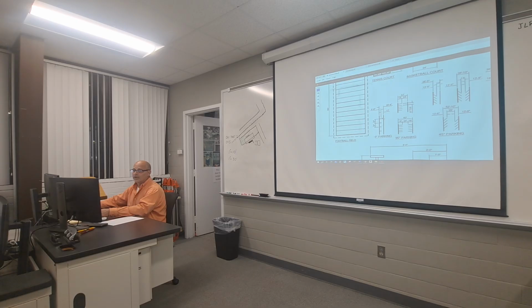So once again, maybe yours has some on the outside. Maybe, I'm gonna give you your number in a minute, but maybe you counted and you were 4 short of how many parking spaces the customer said they wanted. You could just throw some of these along the side somewhere, wherever it fits this design, boom, there's your extra spaces. If you choose to do your standard 90-degree parking spaces, so you're going to be designing a parking lot, and I will give your quantities in a moment. You're gonna be designing a parking lot that has to meet these standards, and yes, I will put a scale on there and check this.